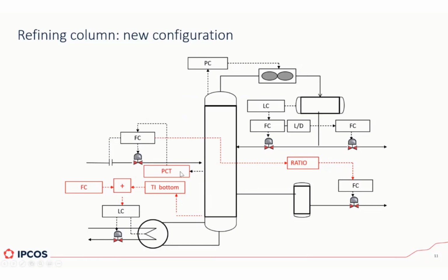And as you can see, it's just not a simple temperature controller. It's actually a pressure compensated temperature controller. Means that even if the pressure changes, you could always make sure that the composition of that sensitive tray is as constant as possible. Why did we have to do that? Because as you can see, the pressure controller acts on a series of air coolers. This project was done in a very hot place. I'm not going to name the country, but let me just say that temperatures of 50 degrees outside were commonplace during summertime.